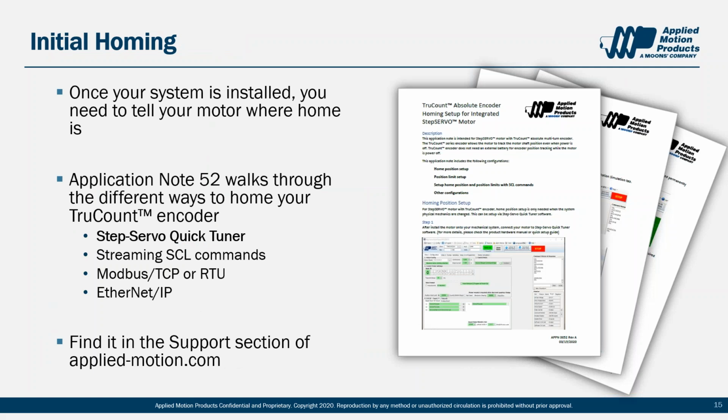When you first get your integrated motor with the TruCount encoder installed in your system, you need to tell it where the home position is. Unlike a traditional incremental encoder, however, this home position is burned into non-volatile memory, so your motor will remember its home position power up after power up. Once you burn the home position into non-volatile memory, it'll stay there.